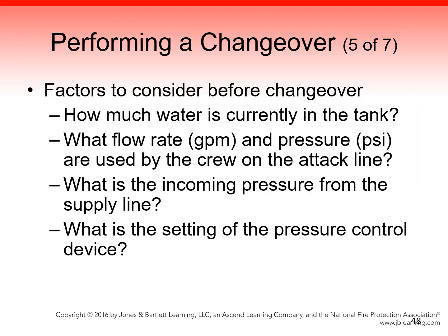There are several factors you need to keep in mind prior to the changeover. How much water is currently in the tank? What are the flow rate, GPM, and pressure, PSI, currently used on the attack line by the firefighting crew? What is the incoming pressure from the supply line? What is the setting of the pressure control device?